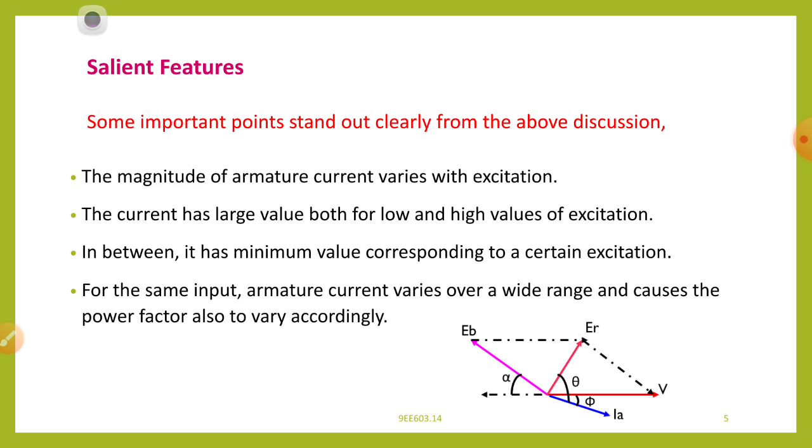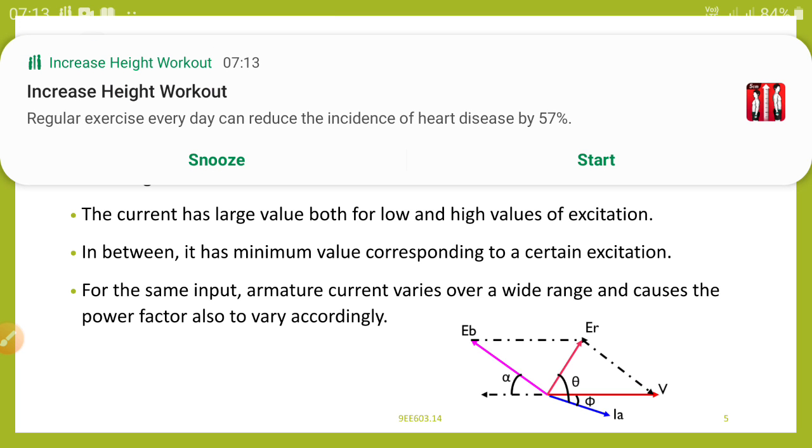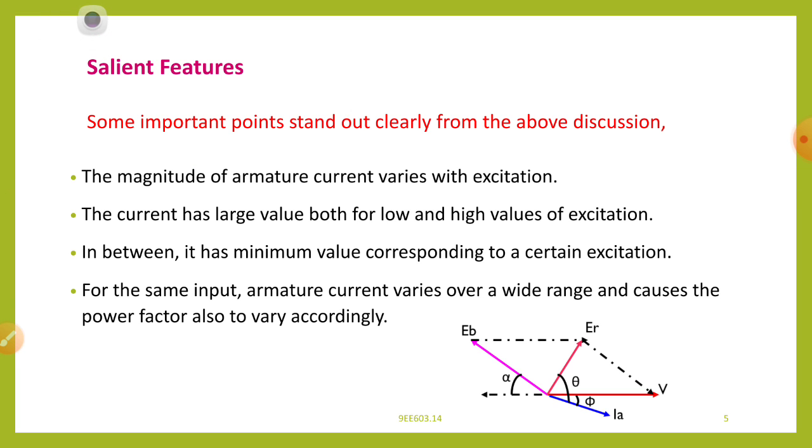Stator and rotor poles are coupled and interlocked, magnetic locking takes place in the ideal condition under no load. But practically there are inherent losses: iron losses, friction and windage losses, and some copper losses to be met from the supply.